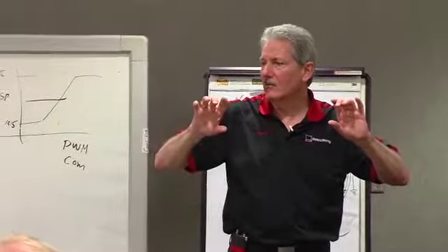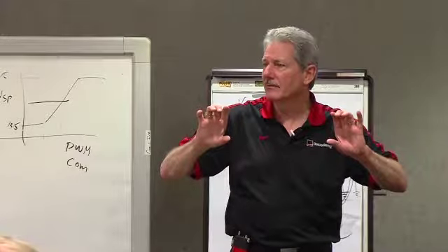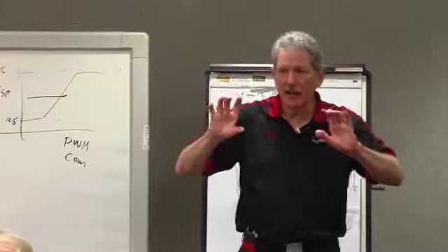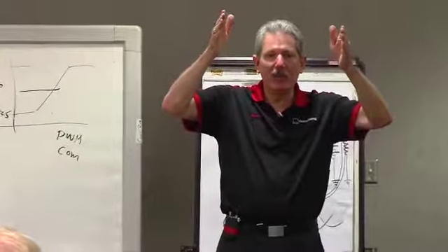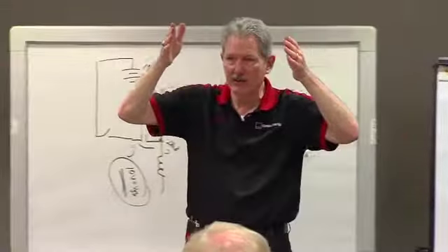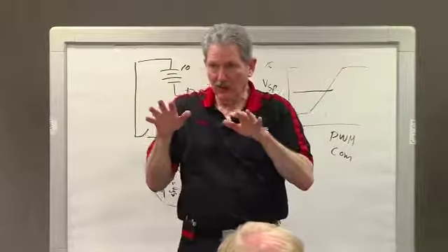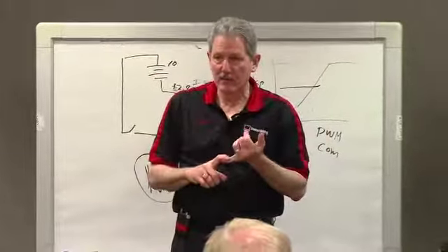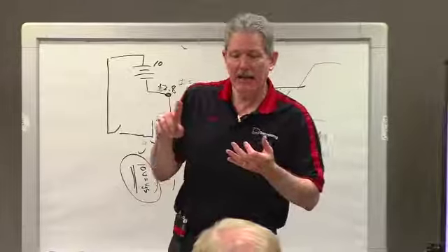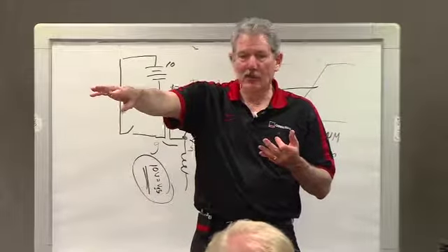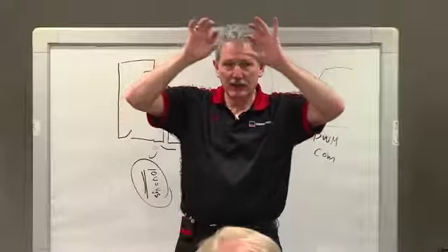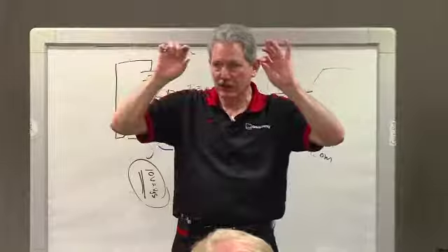Give me another one, Dankert. What's another parameter that's on LIN? Current limit. So I can take all those, and those are 8-bit words. With 8 bits, you can get 256 possible combinations. So now the computer says what I want. I want a load response control of 2.5 seconds, a set point of 14.8, and current limit of 6 amps. So it takes these and it converts that thought into 110011, and it converts all those.